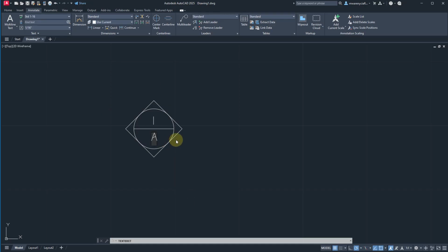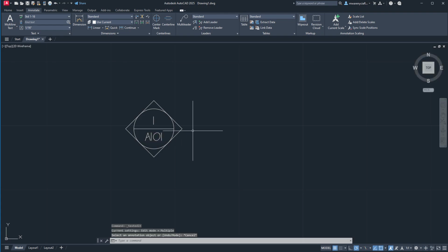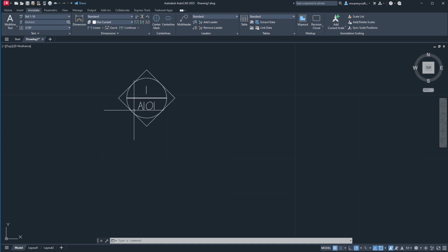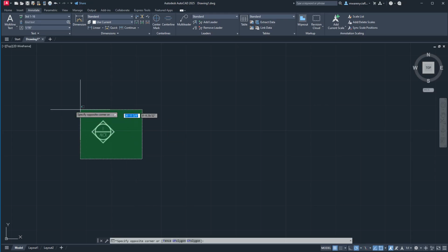And what we'll do is I'm just going to change this for clarity's sake to A101. This will represent the page that the drawing I'm using this for is on, and then this will be the actual drawing number. So anytime you place an elevation marker or a section cut in your drawing, this references where to find that in the rest of your construction document sheet. So if I look at this, I go, okay, this is on A101 or page A101, drawing number 1. And then for elevations, we'll also have a second set of symbols around here. So let's leave that as a default.